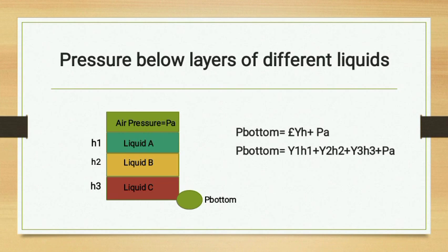or P bottom is equals to unit weight sub 1 times height sub 1 plus unit weight sub 2 times height sub 2 plus unit weight sub 3 times height sub 3 plus air pressure.